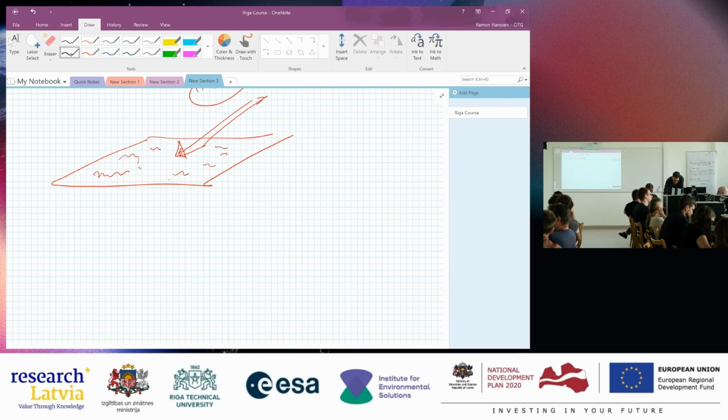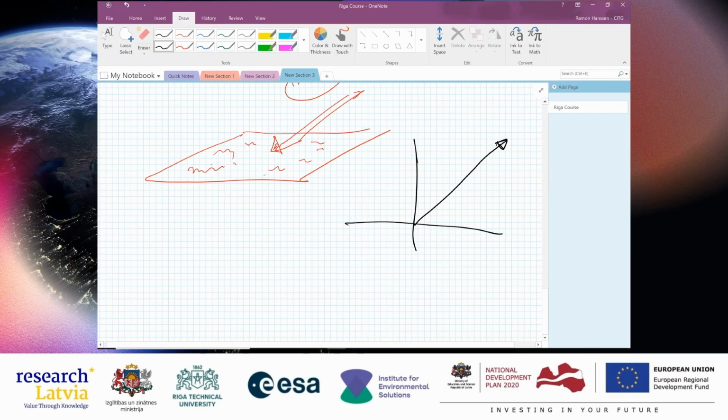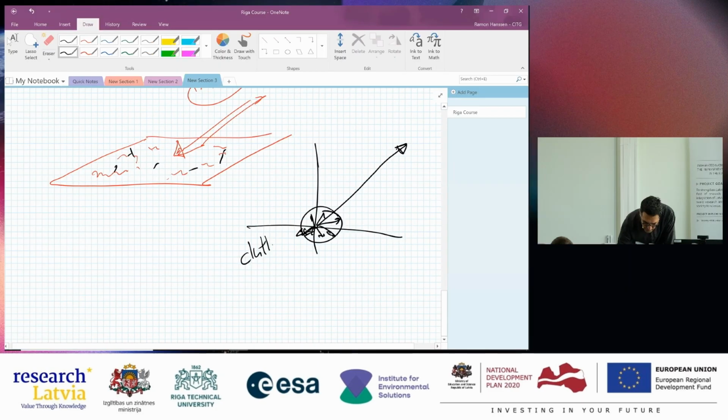So what I will measure then in the complex domain is this very strong amplitude from the reflector and all kinds of little reflections from the ground. These will always be very little vectors, in many different directions. Now this is what we call the clutter. This is a radar term: how much signal am I getting back that does not make any sense, that is not interesting? And this is the signal. So the signal to clutter ratio is the signal divided by the clutter.